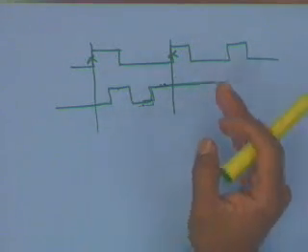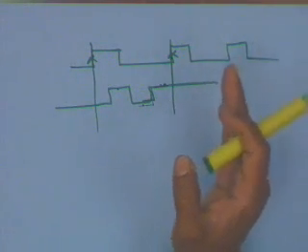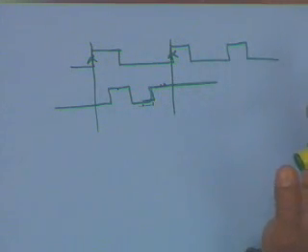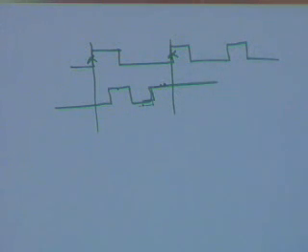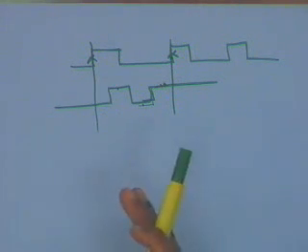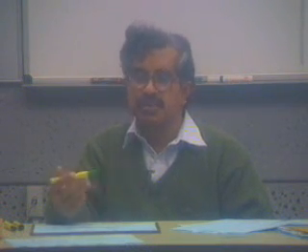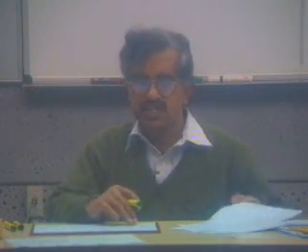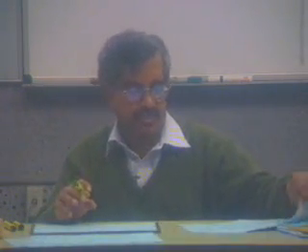So it is actually possible to implement all these designs using a synchronous model of the machine, except that you will be synchronizing the state transitions to the clock. The inputs may be changing at odd times, but you will synchronize them to the clock. In many situations that is not really a big issue. But asynchronous machines, we will point out at the end of this class, have certain distinct advantages, and in some situations they are used. The reason they are not used much more widely is that the design is not easy. The design is complex, and ensuring that it works properly also takes much more effort.